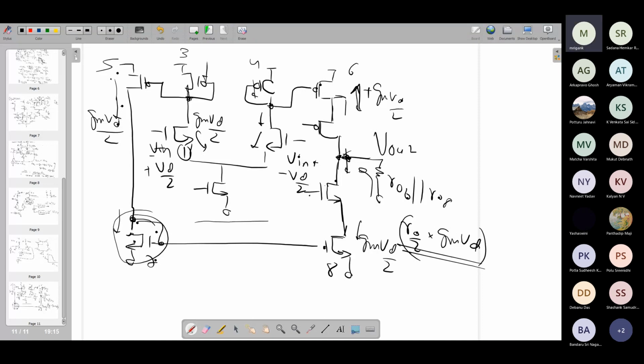You can figure out, right? So for M6 and M8, you know what the small signal current provided is. It is remaining the same, till M6 and M8. The only thing is that now you have these two cascode transistors coming into the picture. And in order to find out the output signal, I need to find out the small signal current flowing to the output in the presence of these cascode devices. So what will be the value? Approximately, what is the order of the small signal resistance at the output now?